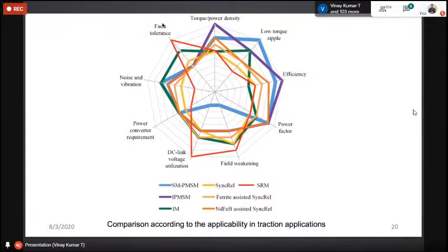Especially in electrical drives applications, even if one of the phases gets a fault, the machine should operate in continuous mode, right? In the case of SRM, generally the stator winding is concentric type winding. It is not distributed. If there is any fault in one coil, you need not replace it immediately. Without one coil also, we can continuously operate the SRM. If you take distributed winding, if there is any problem in one coil, you need to stop the drive immediately and replace the machine, right? That's why fault tolerance of the SRM is more, because of the advantages of concentric winding.